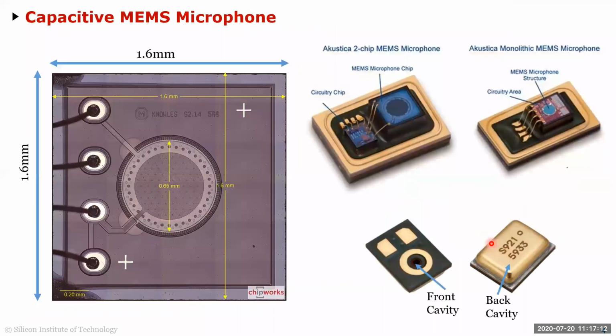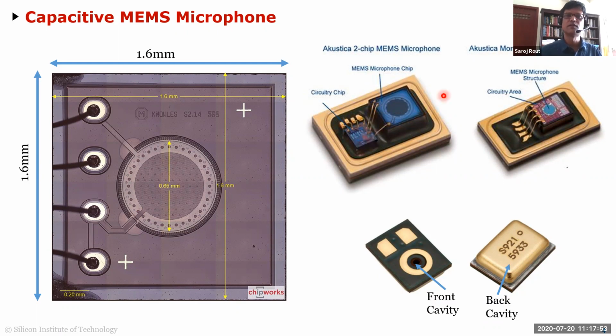Okay. So I'll show you a couple of VLSI systems, how they look. So this is a typical microphone. The microphone in your cell phone, if you break it open, is a VLSI chip plus a MEMS microphone, which is also VLSI, but a mechanical system. It's actually 2 plates of a capacitor with air in between. When you speak, you compress this plate, it changes the capacitance, and then the circuitry converts that change in capacitance into an electrical signal. So it's voice to capacitance to electrical signal, basically how this thing works.